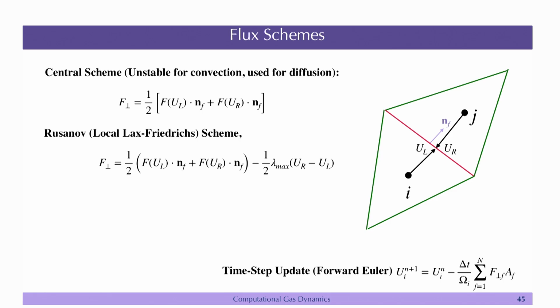So if the scheme is more accurate, then the delta t also has to honor the requirements of these high resolution or high order schemes. That is why, if you want to begin, you can start with a scheme which is very diffusive but also very stable. This is the Lax-Friedrichs scheme, where we have a central differencing of this part, and then you remove this part, which makes it very stable.